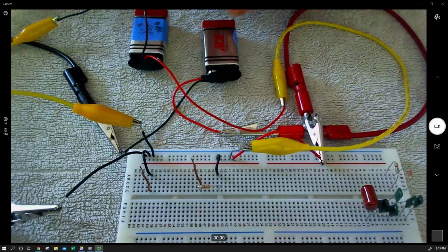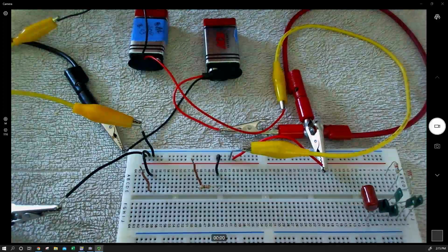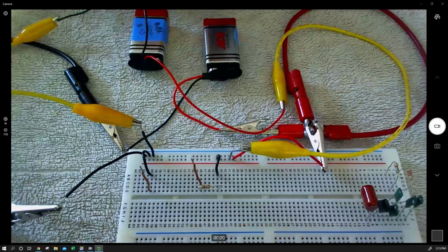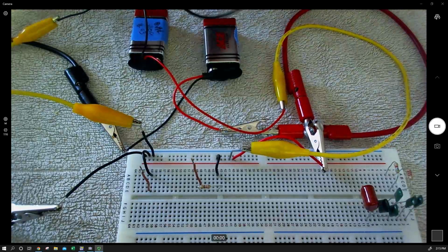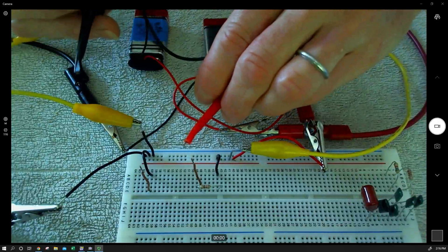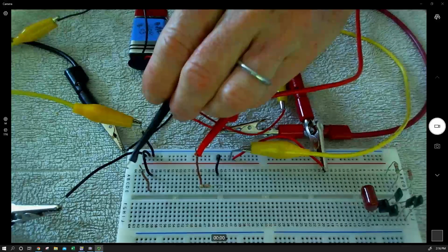Okay, so we're going to make the measurement again with two sources in parallel. We are driving with the same circuit voltage. It's still the nominal 8.63 open circuit, probably much less under load, but now we have two sources capable of contributing current in the event that a single one was being limited by its own internal resistance.